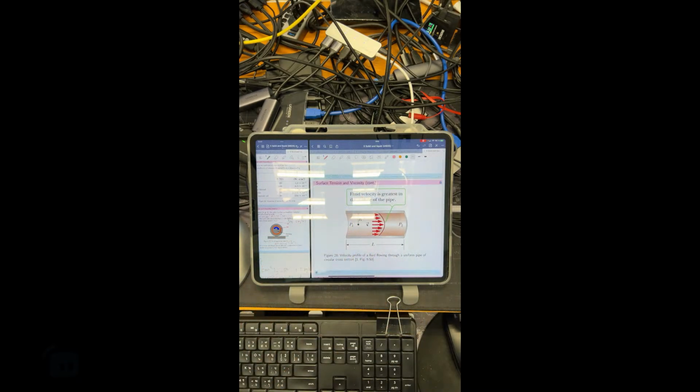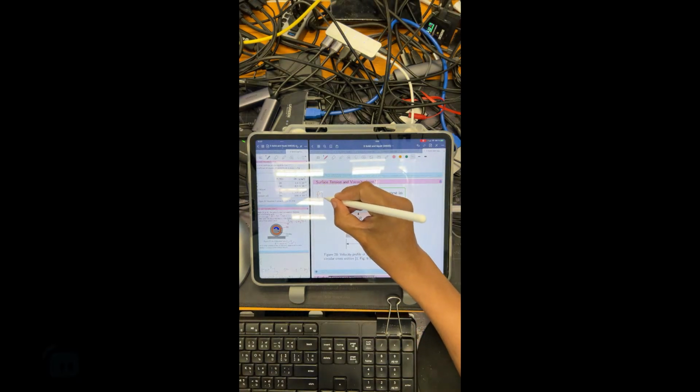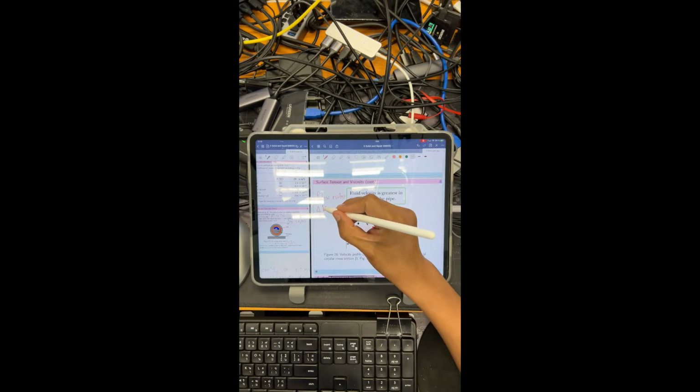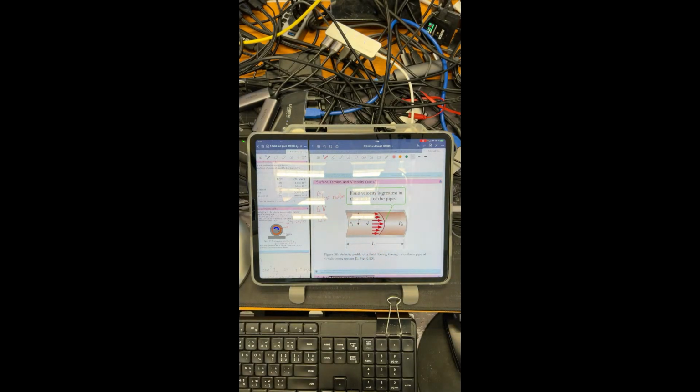So now let's get to more detail of the relation among several factors, right? If you have pressure 1 and pressure 2 here at the beginning, and you want to find the flow rate, okay? What is flow rate? It means delta V by delta T, the volume per time that flows through this pipe. And of course, the velocity profile, you have high velocity at the center, lower velocity when it's far from the center, and very, very low at the border between pipe and fluid.